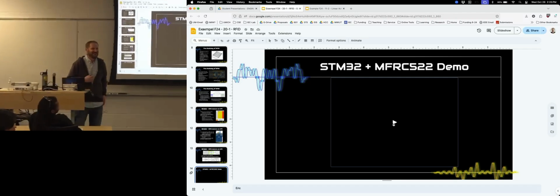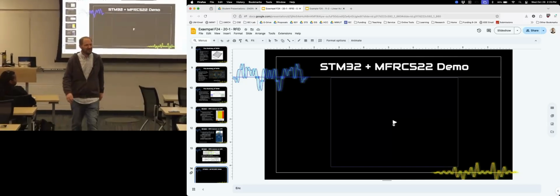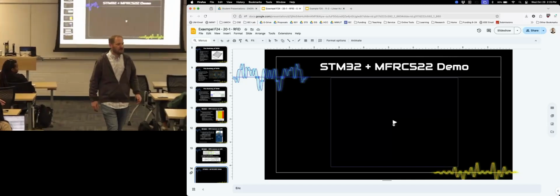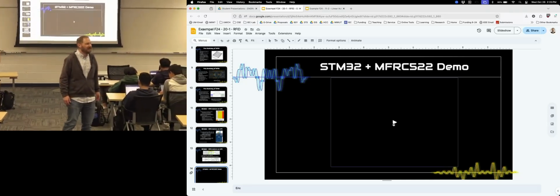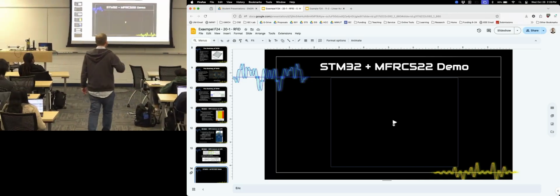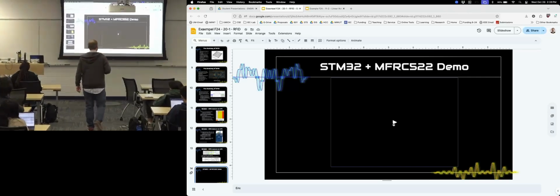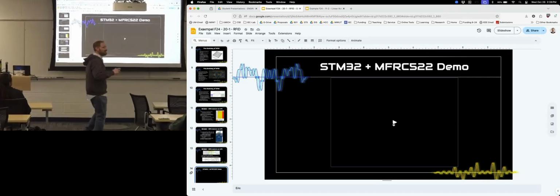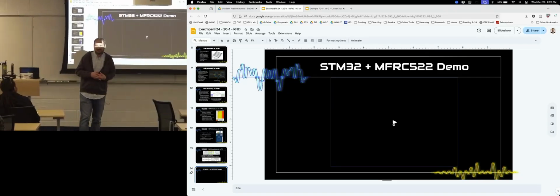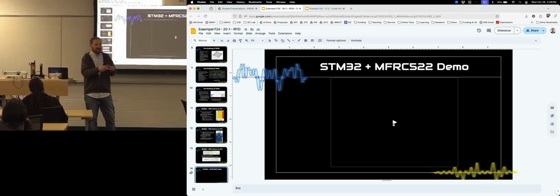For the final project, if you run out of ports on the STM32, do you have to use a PCB then? If you run out of ports? Well, a PCB won't help you get more ports, but you could use 2 STM32s. You could use a GPIO expander, which would use an SPI interface to a module that would emulate multiple GPIO pins.